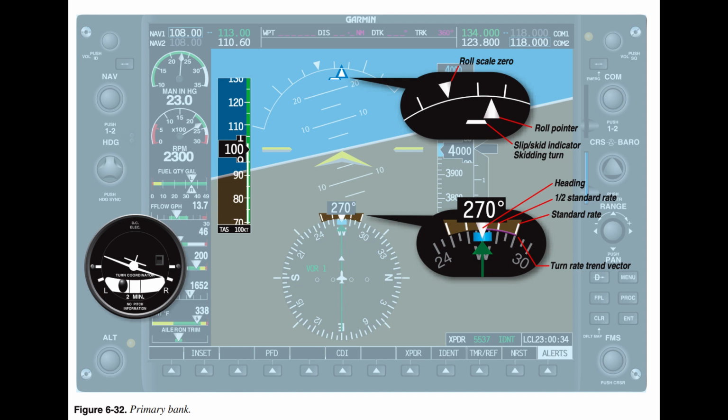How a pilot gathers the necessary information to control the aircraft varies by individual pilot. No specific method of crosschecking, scanning, is recommended. The pilot must learn to determine which instruments give the most pertinent information for any particular phase of a maneuver. With practice, the pilot is able to observe the primary instruments quickly and crosscheck with the supporting instruments in order to maintain the desired attitude. At no time during instrument flying should the pilot stop crosschecking the instrumentation.